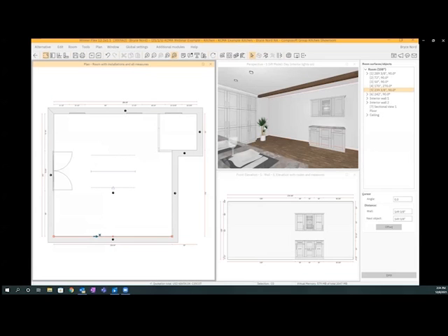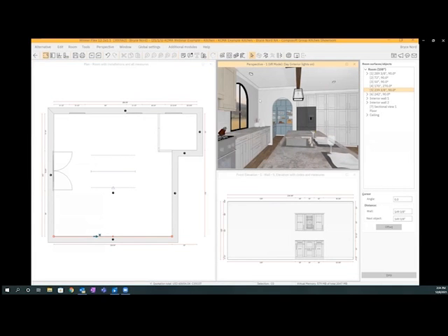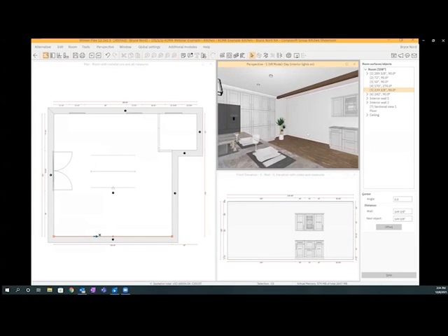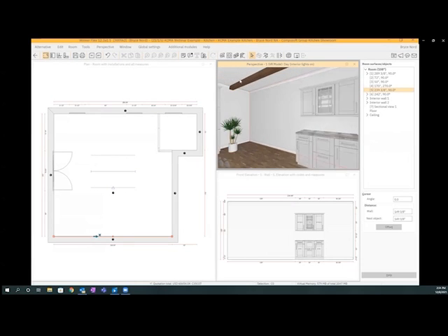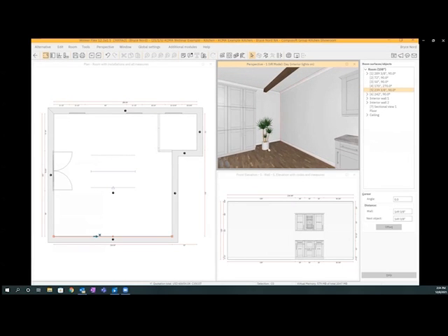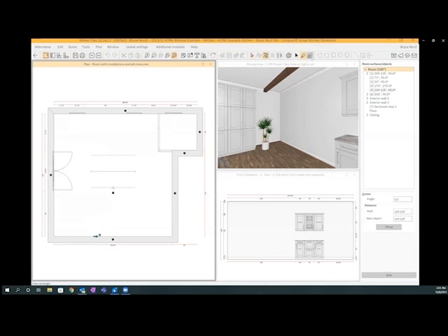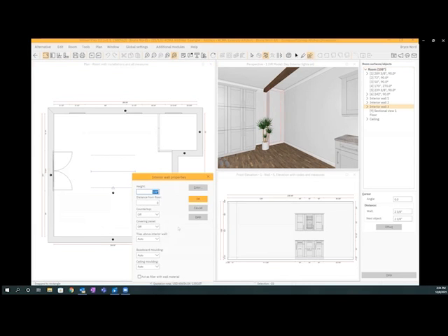Another example I'll show is, let's say we wanted to add in an internal wall like we've done over here. If, for an example, in this back corner, we had a closet chase or a chimney flue that came through here, I could do internal wall, and I can either free draw this like we did on the other section over here, or I can just drag and drop a box, which will make it a part of this room itself.